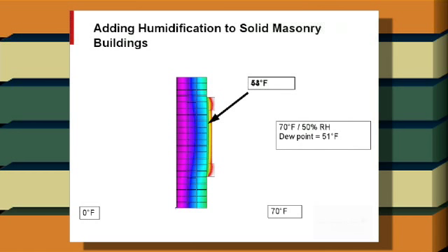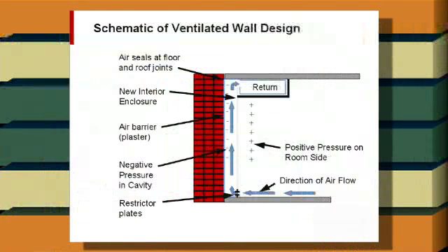And one of the ways to deal with that, and we've done, I think, 2 or 3 projects like this, is to hang the artwork on a separate interior finished wall that you then turn into a return air plenum by hooking it up to your return air and then drawing air through here. That way you have positive pressure, which curators like.